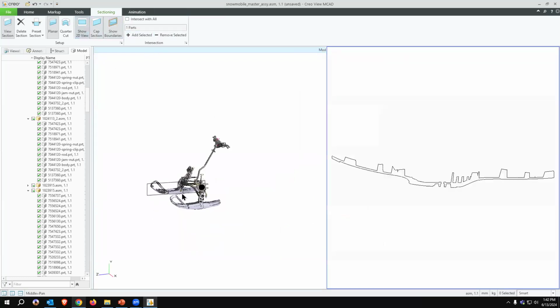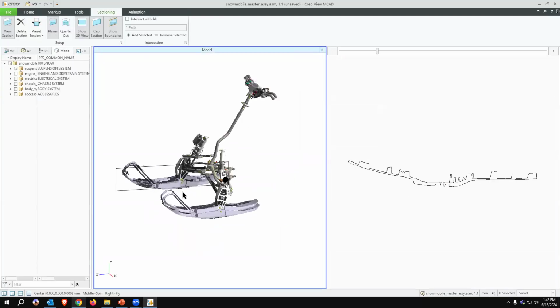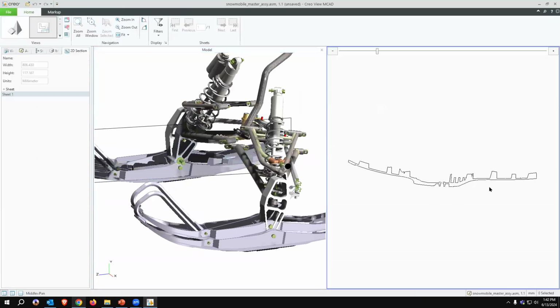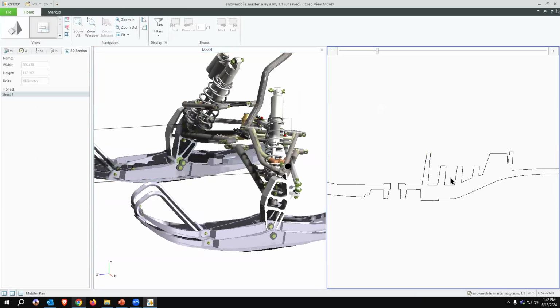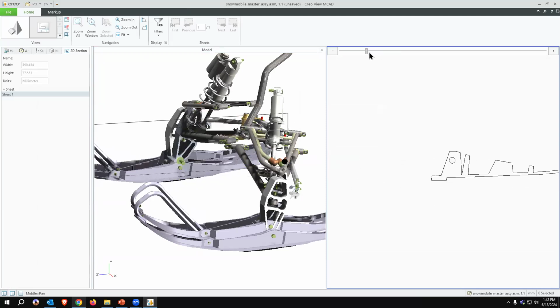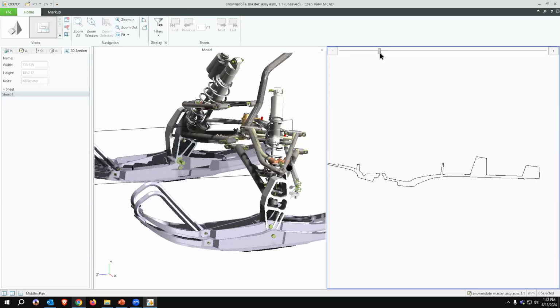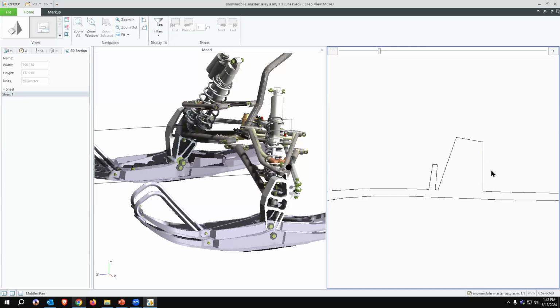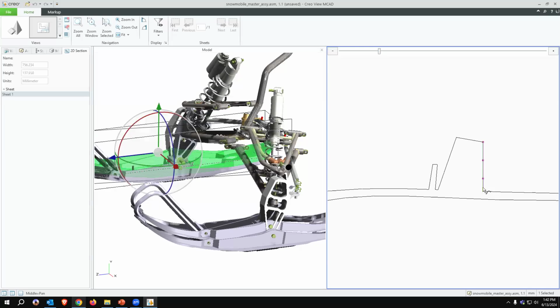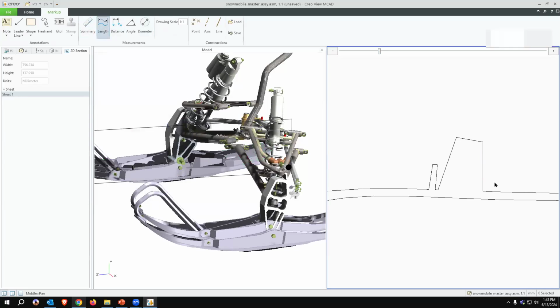So in the MCAD version, I can show what that cross-section looks like. So for example, if I intersect that component at a certain plane, I can see what the 2D looks like. And I can also intersect it using a slider here that shows me what that intersection plane component looks like. Now, one of the things on this intersect plane is because this is a vector component, I have a markup functionality that allows me to, for example, measure lengths.